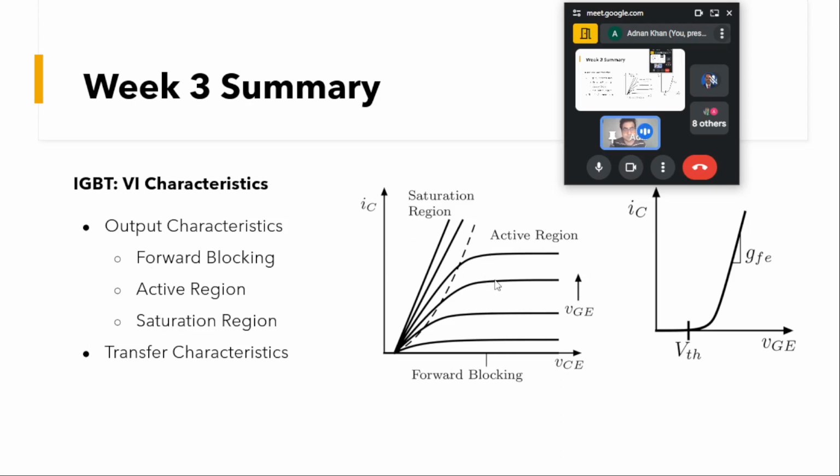Also, what is different from the MOSFET characteristics is that we have a constant drop initially, in the fashion of a diode. After that it will start conducting. Here in the MOSFET we had an RDS(on) that was causing a drop of I RMS times RDS(on). That is one thing that is different from the MOSFETs.